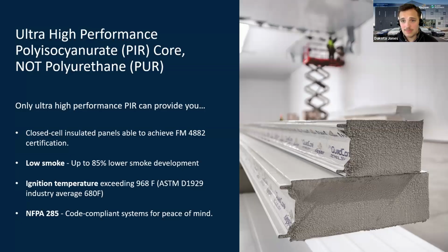But now, as an industry, no matter who you end up choosing for your IMP, polyisocyanurate is going to be the standard. That's like 7.2 on average. As I mentioned, most of the time it's going to be FM approved. And again, its fire performance is significantly better. If you blow a torch at this thing, it's going to char up. Virtually no smoke, much, much safer to be around. And that's why, as an industry, we've moved away from polyurethane.